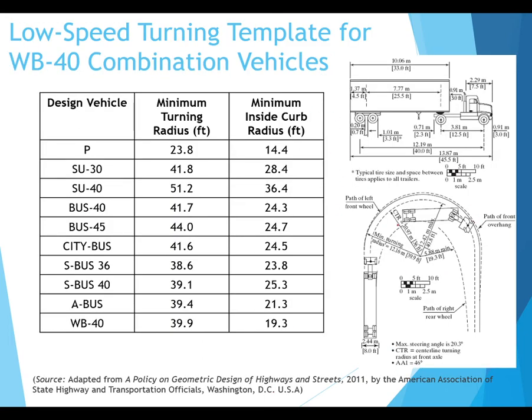This is a WB40 where we have a truck that's turning around. You can see this is the first axle and this is the last axle. Since they are in two different lines, when it turns, this is what we call lane widening. So this is not a regular lane width. We have widening because of this kind of problem. So when we have an exit at an interstate, when we have huge interstate trucks, trailers, and so on, we figure out what is your turning radius out of this simulation.